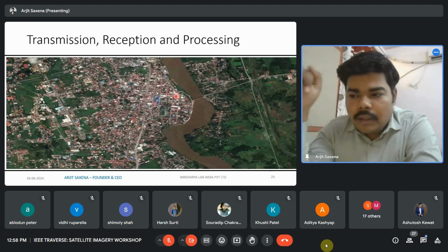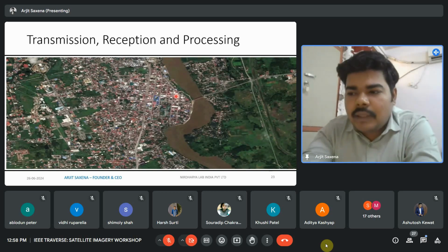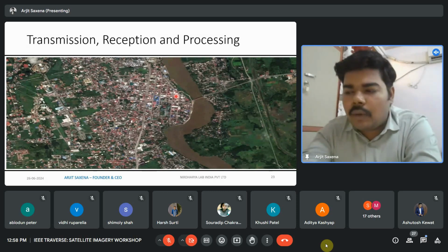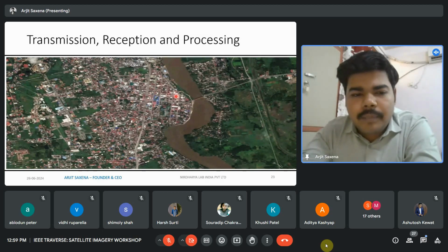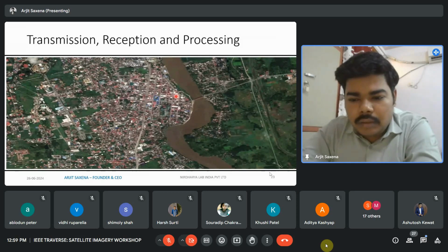But again, that module is dependent on your design perspective, like the sensor you are using, the wavelength, and the frequency which you are using. So it is dependent. It can go up to 20 kilometers. I have tested it, it surely will go up to 20 kilometers. In most cases there is an error, so it will go around 15 or 12 kilometers. So just check the frequency or check whether your circuit is right or wrong, then you will have proper data. Kahana, is it clear?